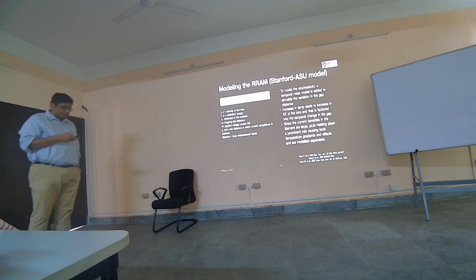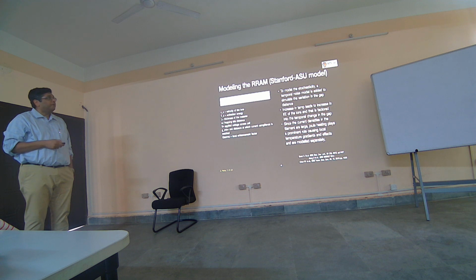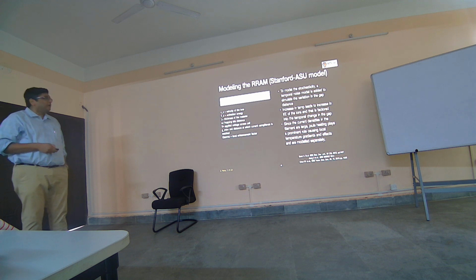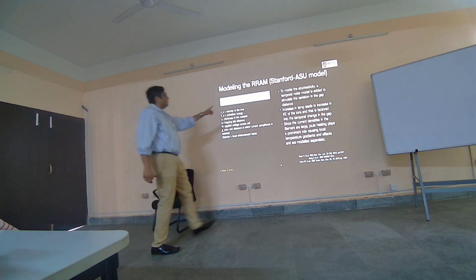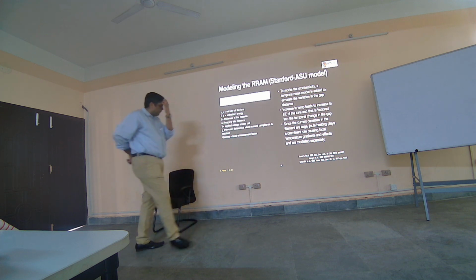The way we model it is the rate of change of the gap is related to the energy required for the oxygen vacancy, and it's also related to the applied voltage. So the higher the voltage, the faster the gap closes. It's also related to the length of the material, which tells you how much gap space is remaining, and the temperature, obviously, since this is all thermally driven.